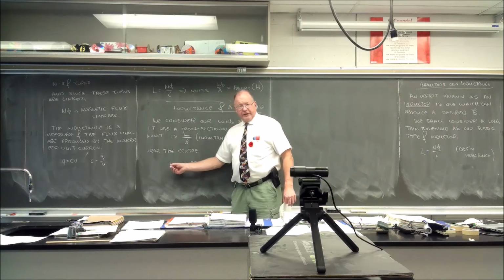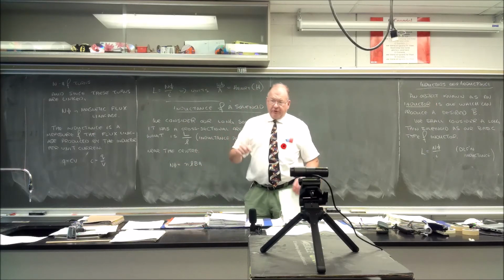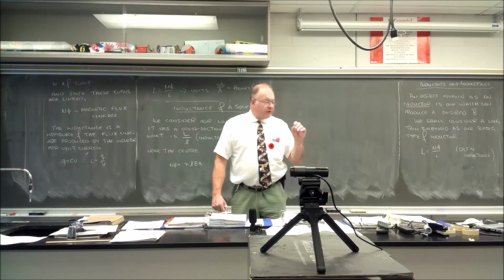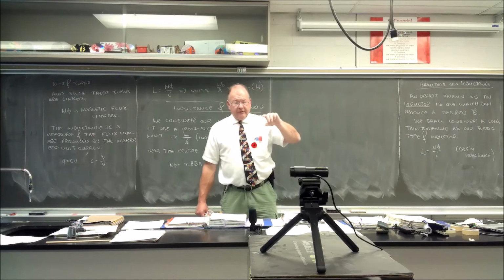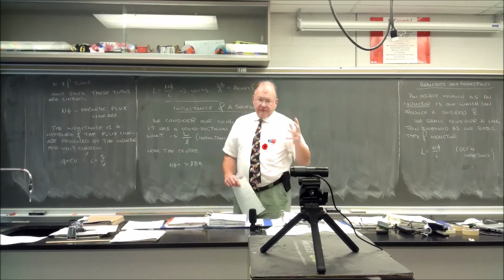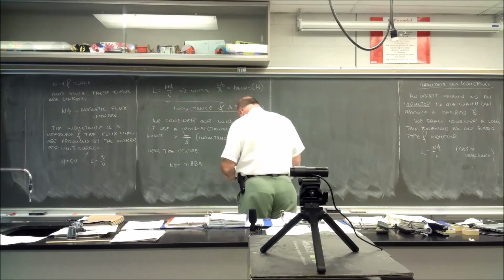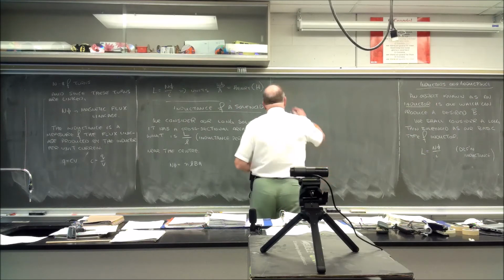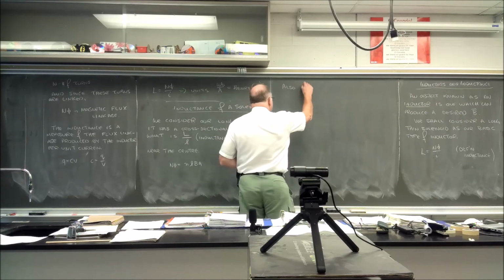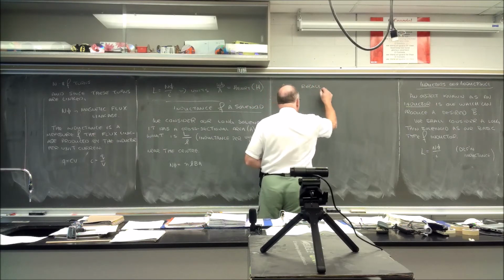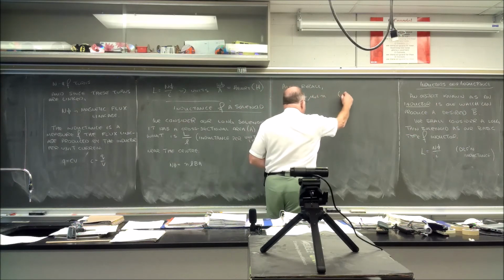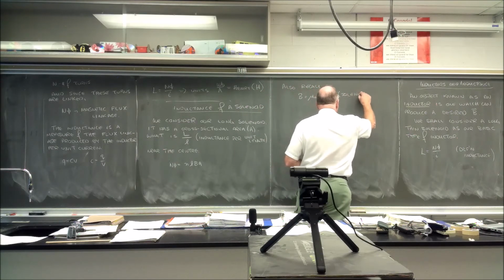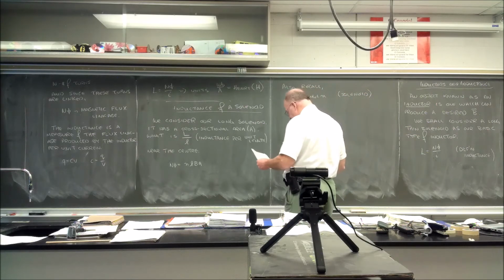Just having all these coils together is just what we call a flux linkage, because the flux is linked between the coils. Just like you saw when I did the solenoid originally, the magnetic field goes through them all, not through them individually, and so they're kind of linked by this magnetic flux. So that's where we're coming from on that. Alrighty. Also, recall that ominous word, B is equal to mu naught I small n, and that's for, of course, the solenoid. And that's near the center and all that.